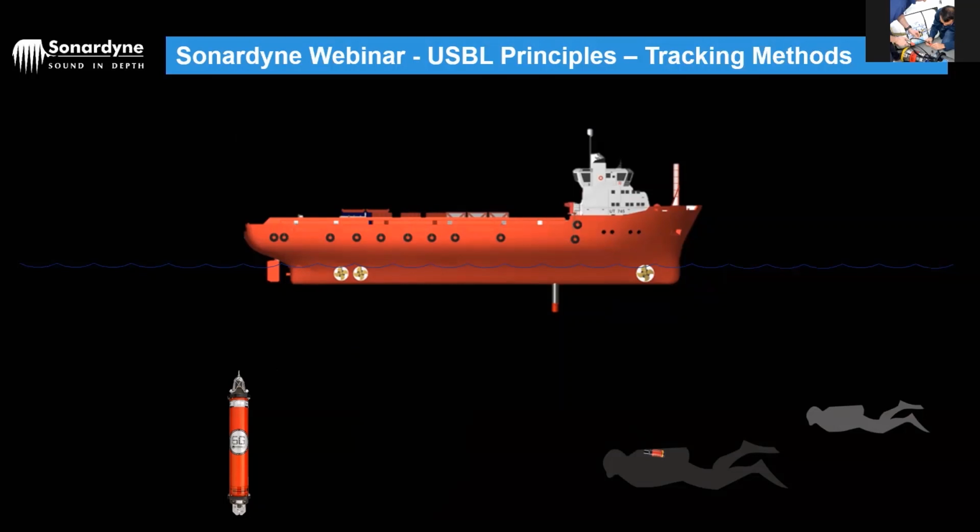Okay. Now the communication that's happening is an individual interrogation signal, or IIS. All right, it goes into the water, and that IIS is basically using the beacon's address. All the beacons will have a 4-figure number for their address. The first 2 numbers are their family group, so you could have all your beacons set to 21-something, and then you'll have up to 14 beacons in different channel numbers. So 2101, 2102, 2103, etc. So they all have their own individual phone number, if that makes sense.